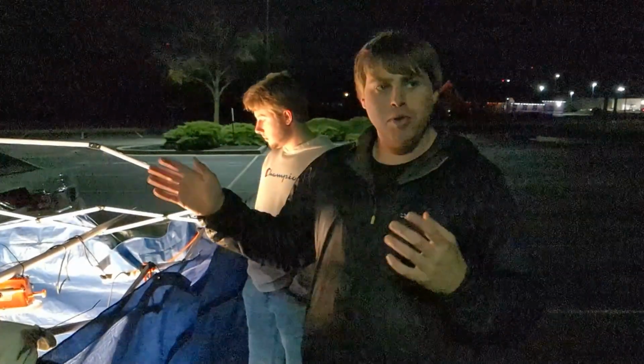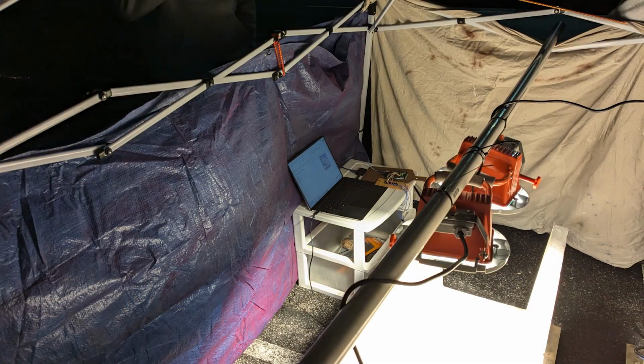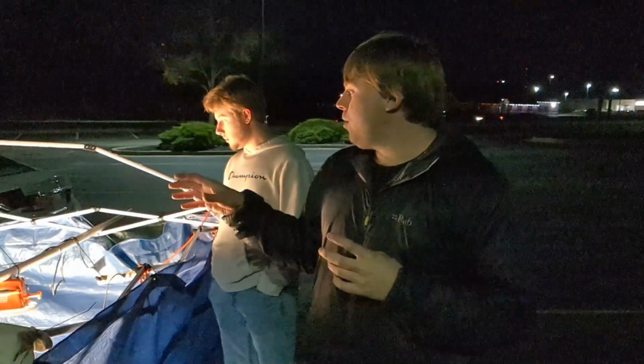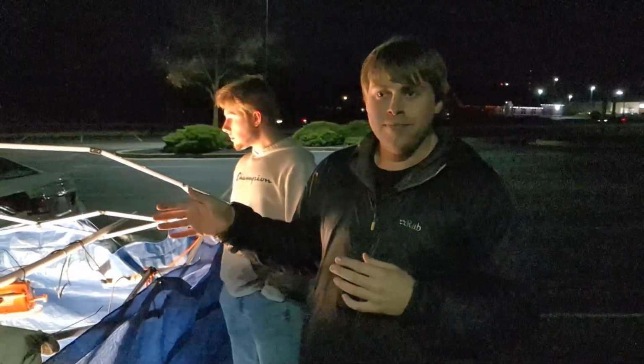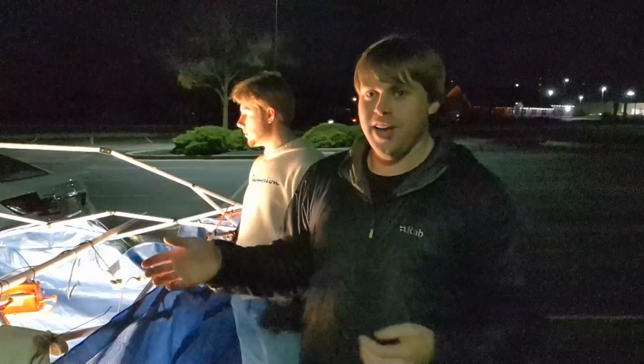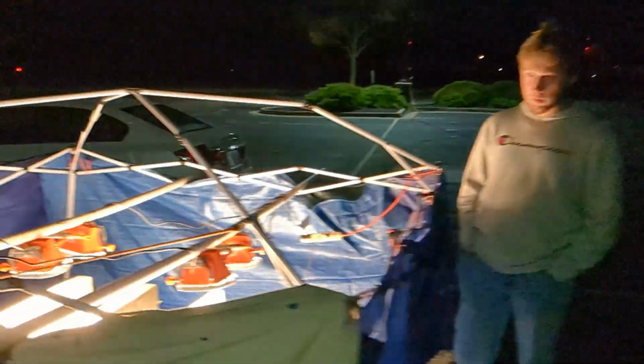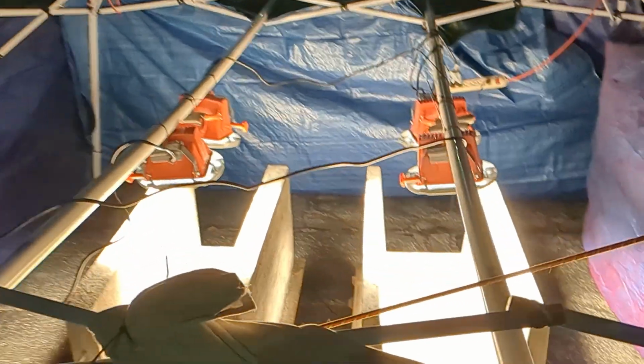We've got both Arduinos hooked up to our sensors and our concrete, measuring the temperature at the walls, and we're going to log that over time. We're taking a data point every 15 seconds over the course of the 6-hour test. So this is the setup, and we're going for it.